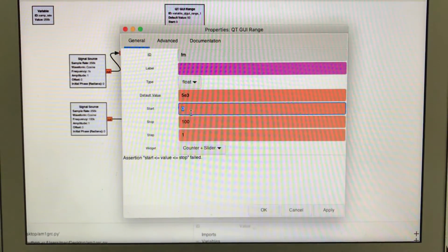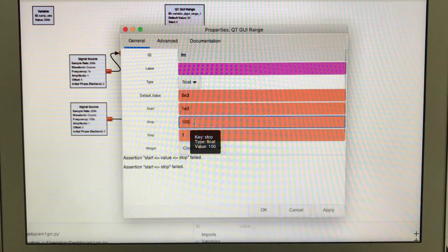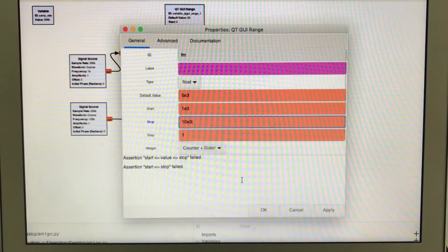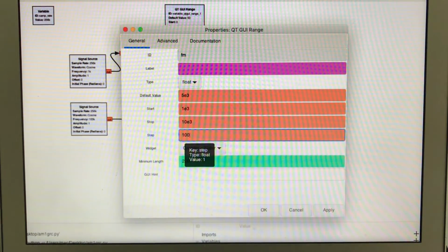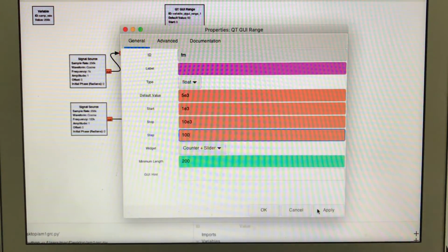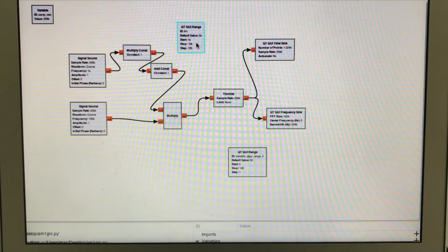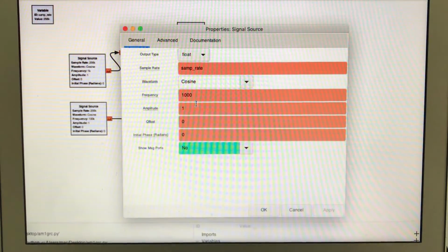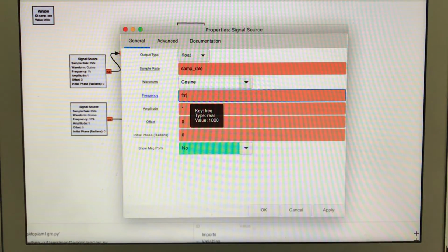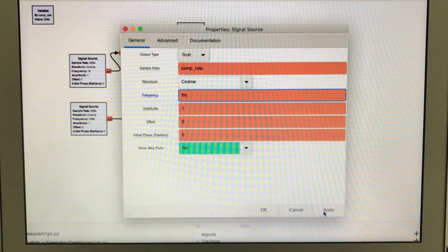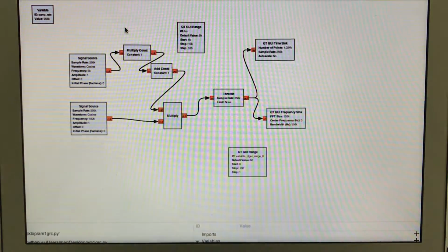And I want to have a start frequency of 1e3, and let it go from 1 all the way up to 10 kilohertz. All right, and I want a step size of 100 hertz. So this is FM, which is for modulating frequency. I'm going to simply go here and call it FM. So now when I run the flow graph, I'll be able to change my modulating frequency using my slider. Okay, let's just close this.